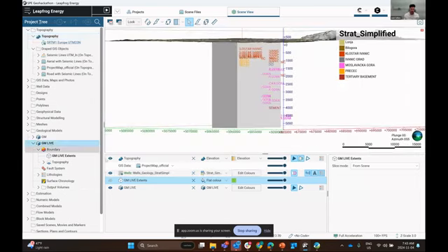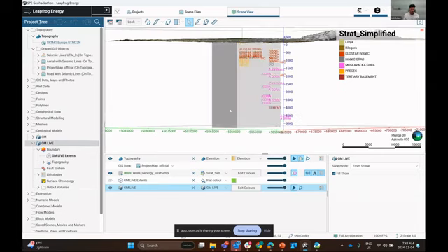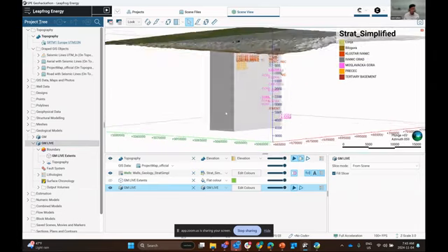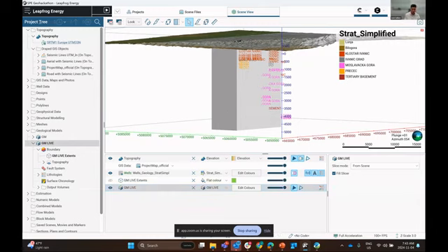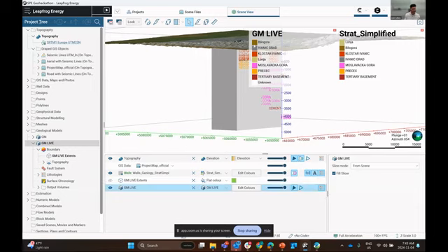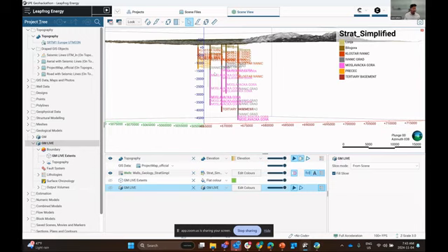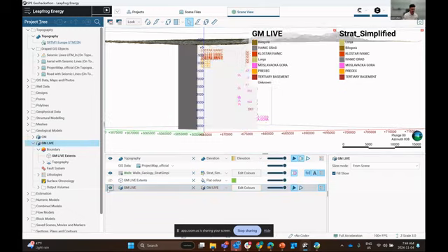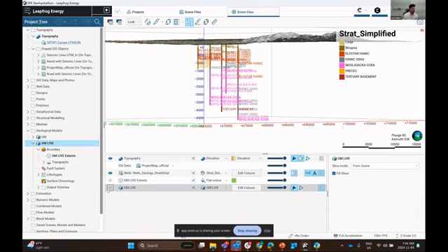So we've got this geologic model. We can drag and drop that GM into our project, and you'll notice that it's just kind of this gray volume of rock. If we press the legend right here, this gray volume of rock represents an unknown lithology. And the objective of this next task is going to be to construct representative surfaces for geologic contacts and then activate them, which will essentially cut the volume associated with that unknown volume of rock that we see right here and replace it with that representative geologic contact.